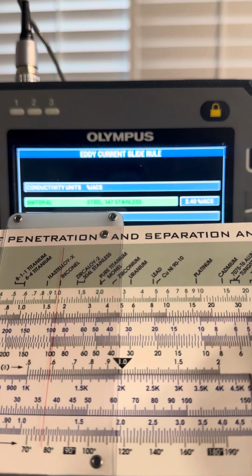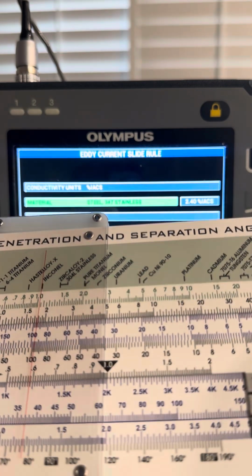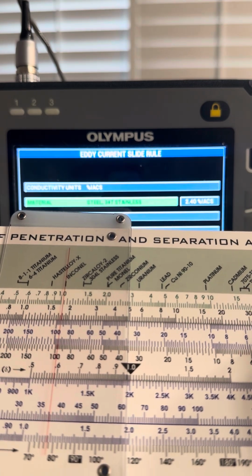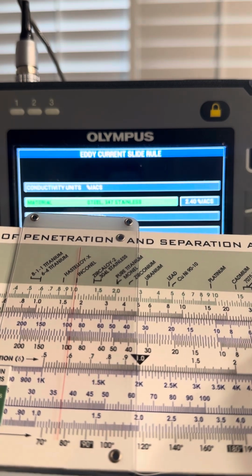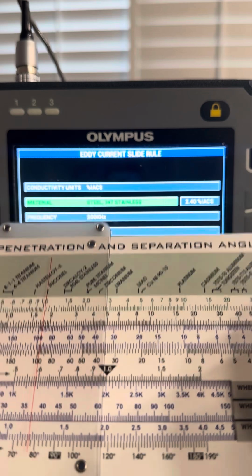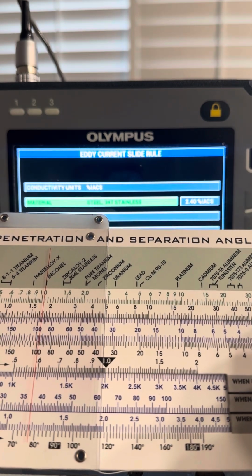Here, you can go anywhere from 0.1 megasiemens per meter all the way up to 100 megasiemens per meter. Or in IACS, you can go from 0.2 IACS all the way to 150 IACS. And for resistivity, you can go from 1,000 micro-ohm centimeters all the way down to 1 micro-ohm centimeter.